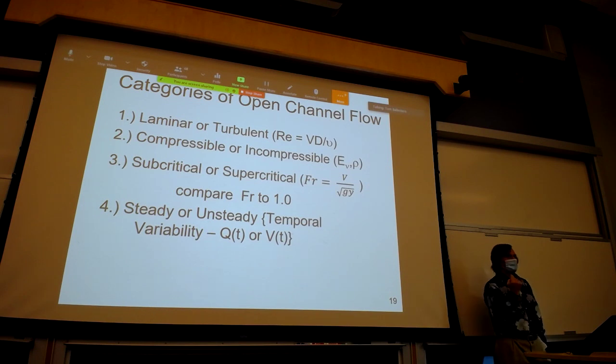Unsteady flow, think of a dam breaking upstream and this floodway moving downstream, and as you sit there fishing, the water level increases and the discharge is increasing and the velocity is increasing, cross-sectional area is increasing. So what you have is temporally variable variables in this Manning equation.